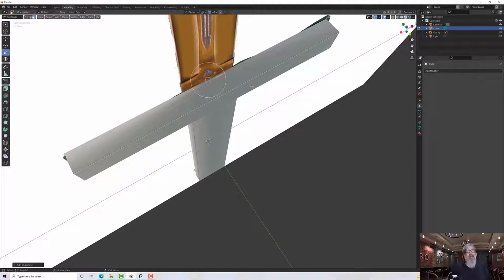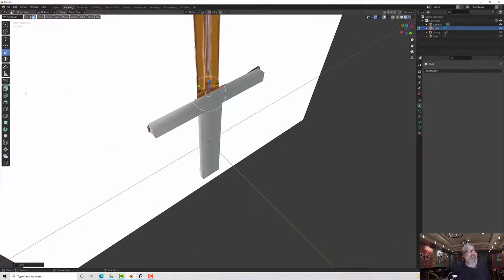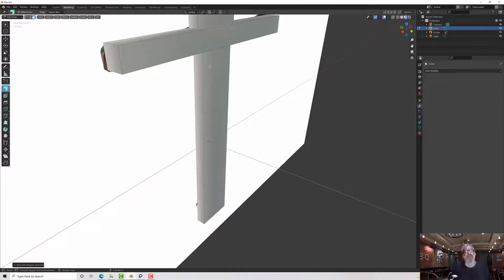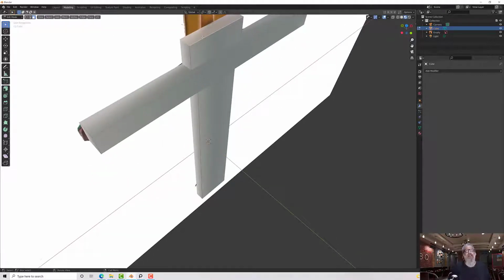and then I'll use my scale tool, and I'm going to bring that in on the red handle and on the green handle, and then we'll add our thickness. So again, we'll extrude along normals, and I'm going to drag that up there. Now before I go too far, because I couldn't see it very well, I haven't scaled it very well. So let's go to selection first, and I want to select everything that's connected to that polygon. So I believe that's Control L.